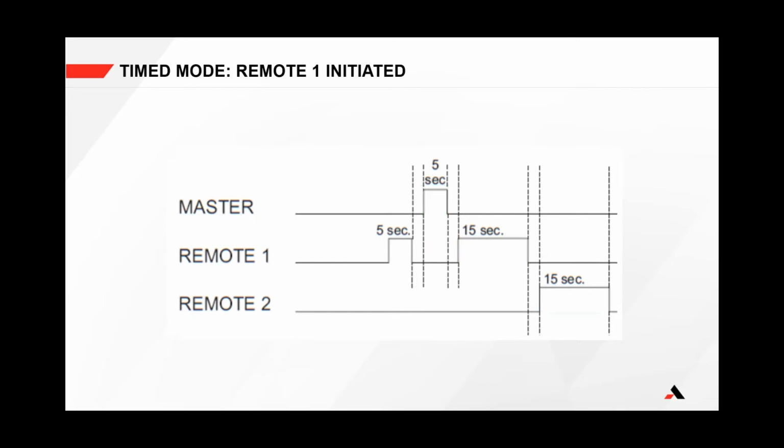to the remaining remotes. Time mode checkback tends to be less susceptible to noise due to just being a single pulse of a specific duration, but takes longer to complete. It also has the limitation that only the initiating UPLC will generate and clear alarms.